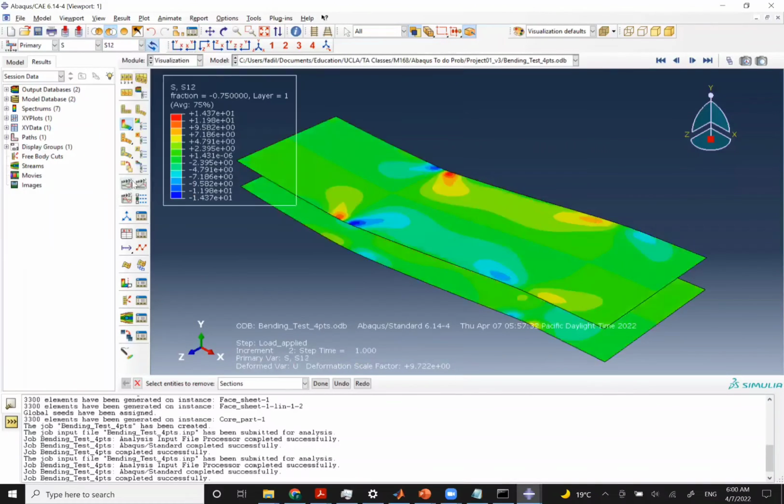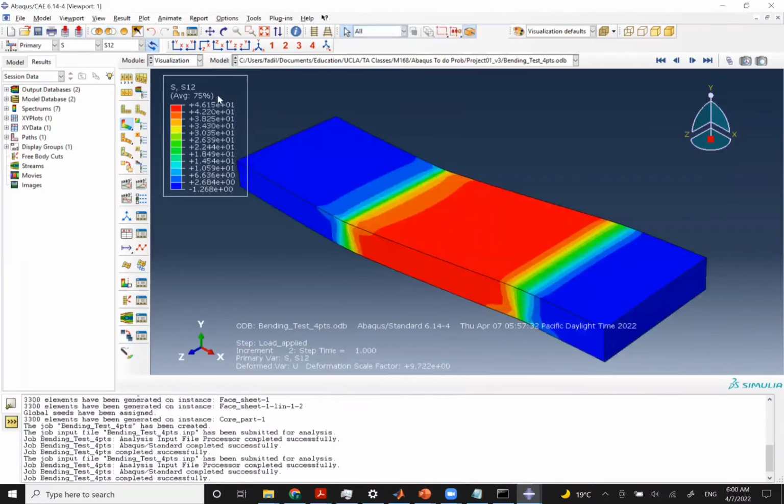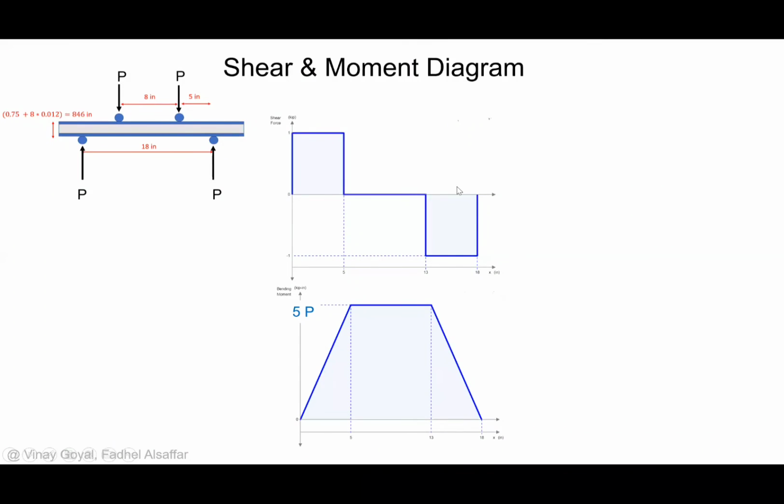the shear, and the shear for the core. So this is the core, and what we see here from the core, first this here is almost 0. See the transverse shear. If you can see this dark blue, and you look at the forces here, it's 1 or 2. I mean not the forces, the stress is 1, 2 psi, which is very small values, and values that are close to 0.